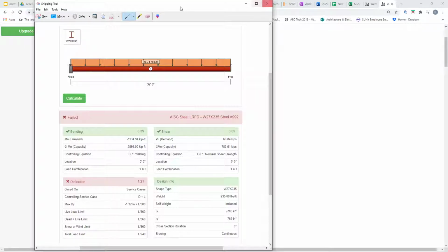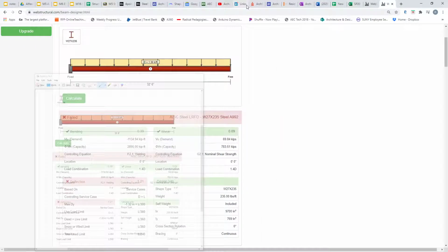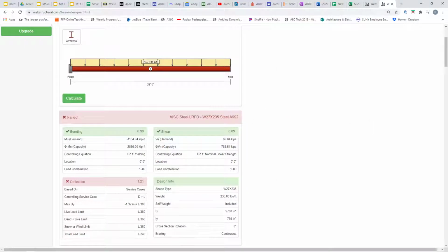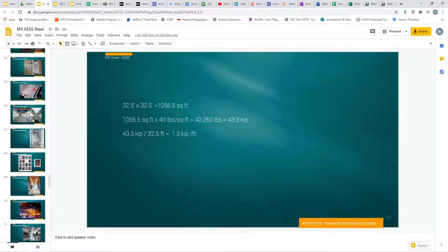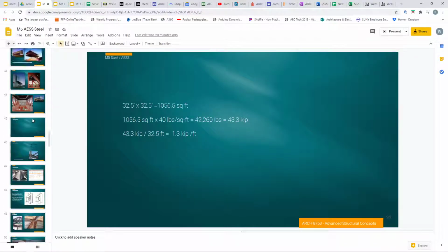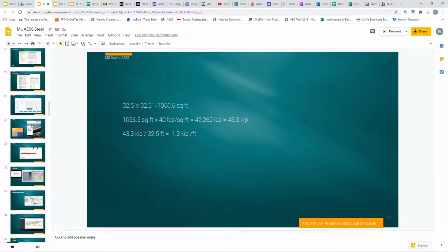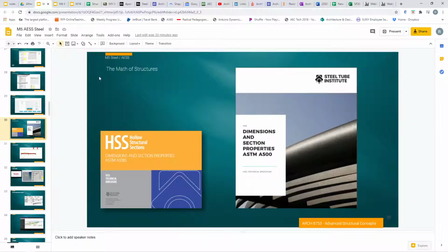Now, if you're interested in not doing exactly what I have laid out, remember you could look at trying to calculate the size of a column by using the charts that I had suggested in our lead into this. You could go to these tables and just take the basic load that we've calculated that's already indicated on the drawing.